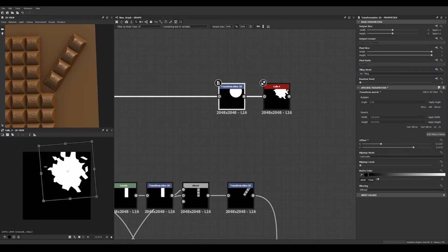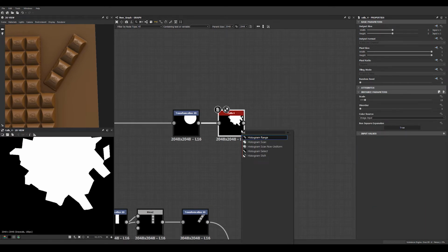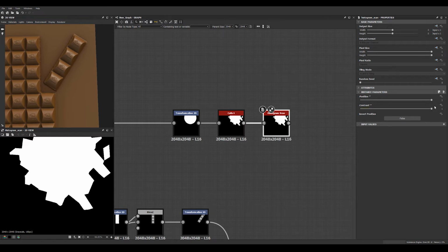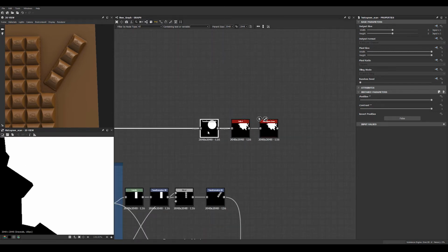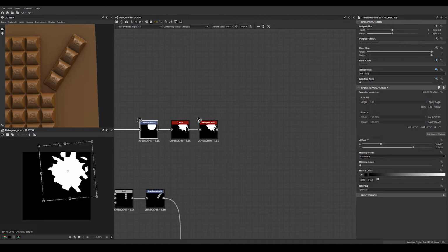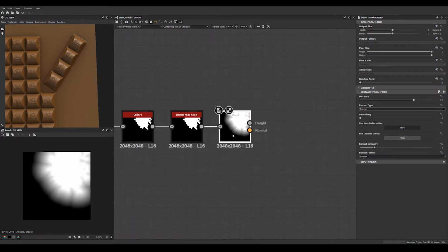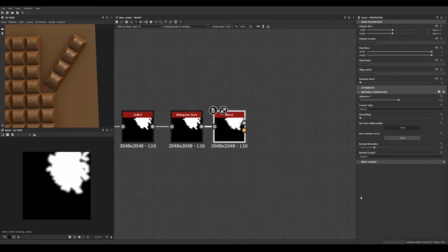Do something like that. And to eliminate any grayscales in here, we just run a histogram scan through this and just kill those, because the way I move this around, sometimes I get some half gray areas. And we don't want these kind of holes either. So we want a nice solid edge, if we can get one. And then we're going to run this through a bevel node, and just set this down to something low. Can add a little bit of smoothing on here.